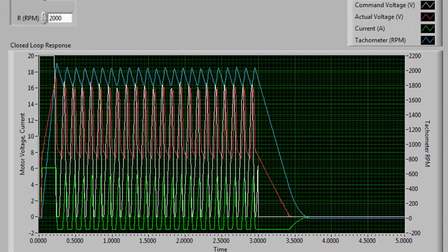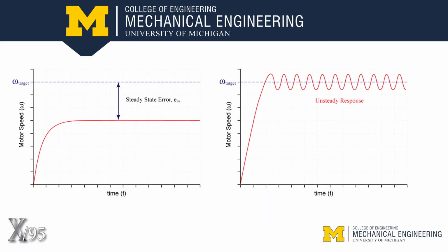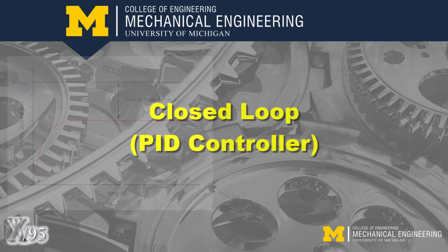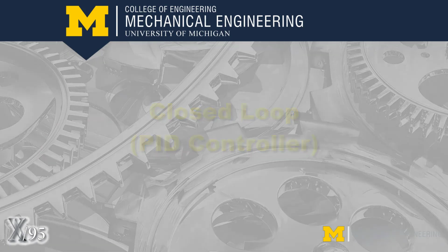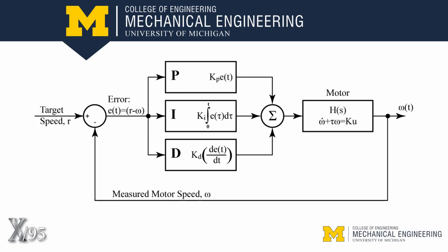Vary the proportional gain and note the trade-off between steady-state error and unsteady oscillation, which is inherent with a P controller. Depending on the instructor, you may investigate the benefits of a full PID controller.